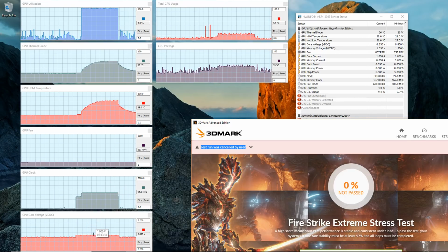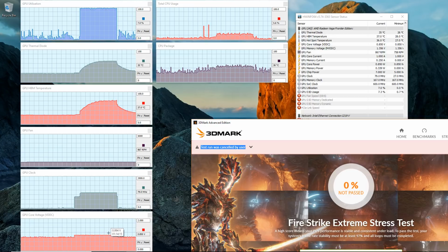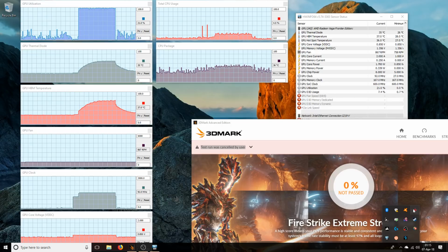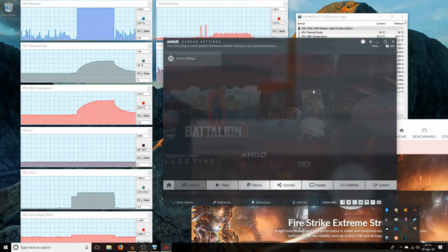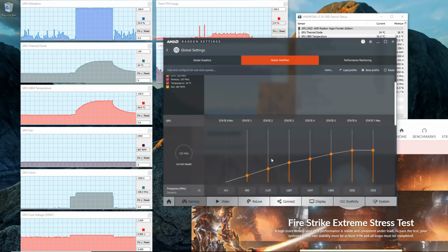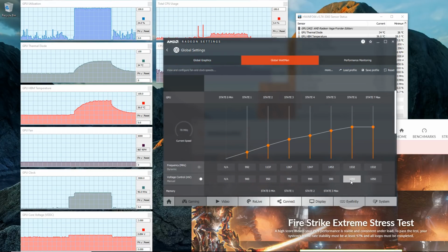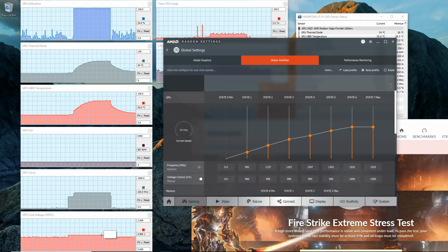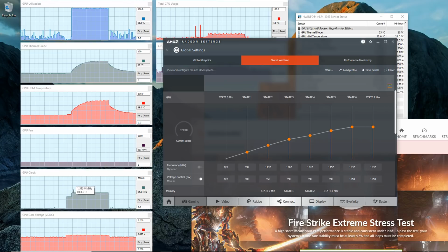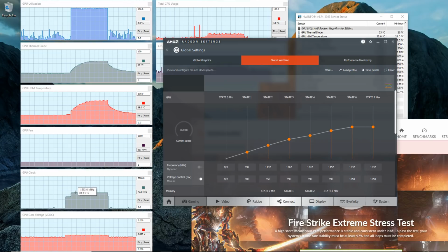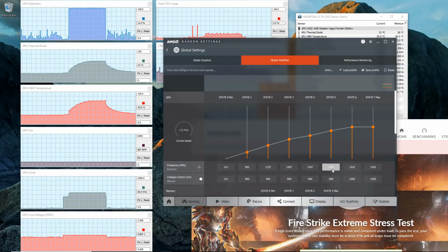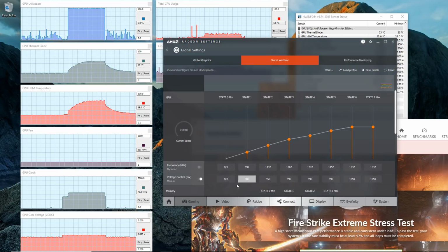And you can see the core voltage here is right at about 1 volt. So that does correspond with more or less what I had placed into Global Wattman. So I can see here that this 1532 at 1050 is most likely where it was operating. What you'll note though is that it's now obvious that it's running in state 6 or state 7. It's not in state 5 anymore, because if that was the case, it would only be 1452 megahertz.